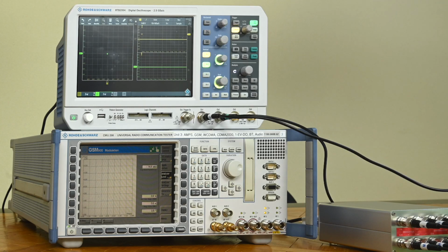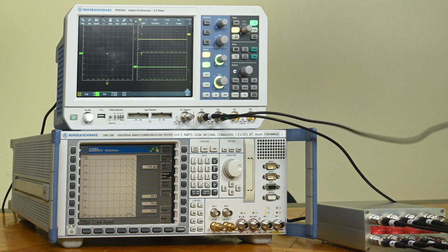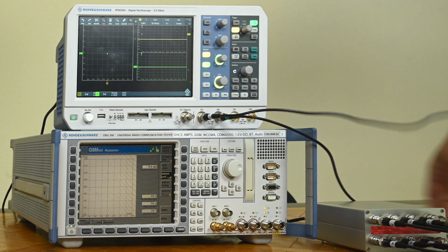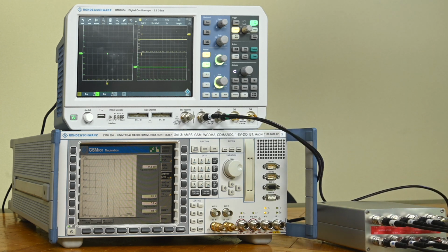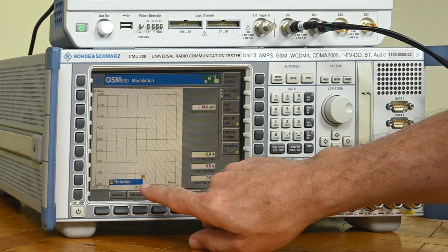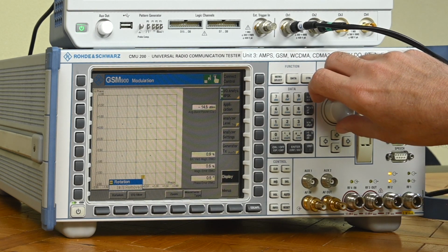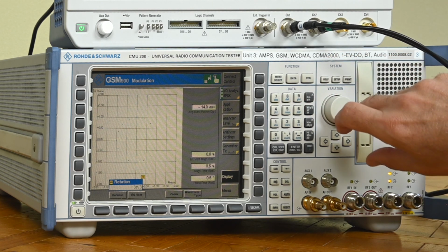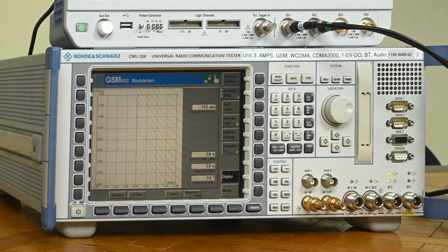I now want to go and look at the IQ channels, and it's a similar exercise really, because we're again monitoring and inserting something in the signal path. I'll try to go a little bit quicker now. I'll go right away to the interruption of the signal path. So again, I've got a constellation diagram here. I have chosen a diagram without this removal. That is a specific thing that has to do with pulse shaping in GSM and EDGE signals. This is going to be easier for our experiment, even though we see double the constellation points.